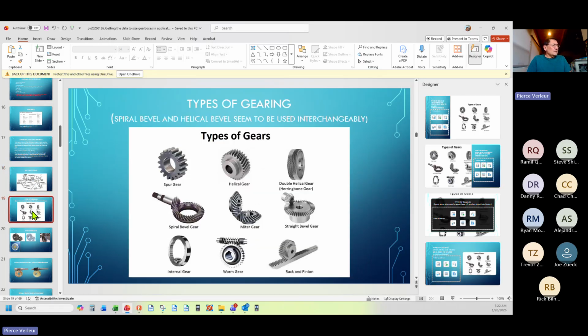Now, these are the types of involute toothed gears. And the spur is most common. The helical is a refinement on the spur. Here's a refinement on the helical. Why refine from spur to helical? Primarily noise. The efficiency is roughly the same. I find that torque ripples less with a helical gear versus a spur gear.